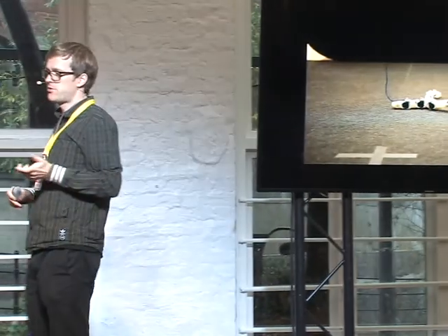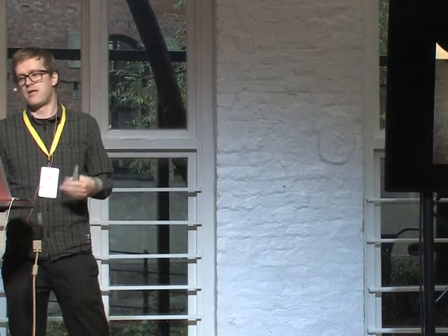We have that connected to a computer, but it's not as easy as that, because if the cable is too long, it will stumble in its own cable, and the process is broken. And if it's too short, then it will not be able to move freely. So to do a lot of training and evaluations with this robot, we needed to make this servo-controlled cable dispensing system, which gives more cable to the robot according to how far away it is. And you can see now when it gets a bit far away, you'll see an interesting thing. It was kind of dropping dead, and once again.